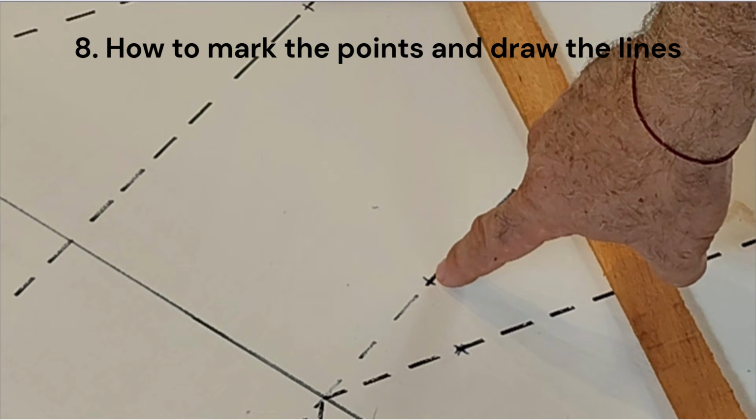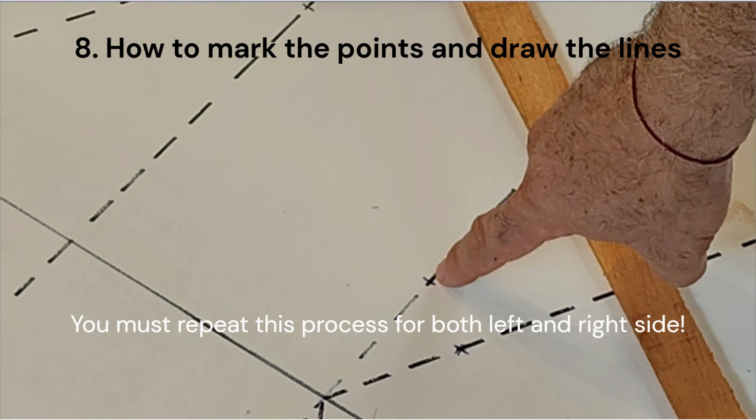In our table for Station 3, we have a deck beam as well. This depends on the station and your boat design. You must repeat this process for both left and right side. This is to be able to put the mold or real station on top of the lofting table.